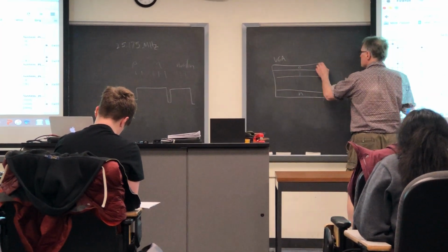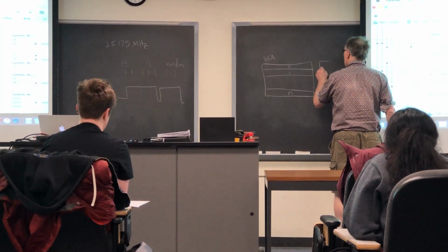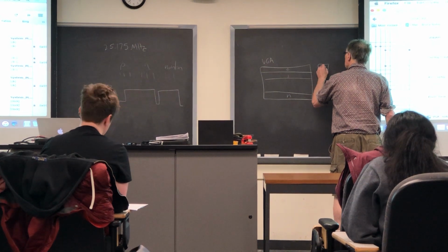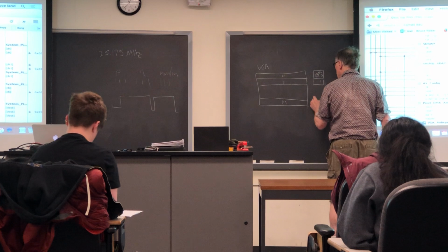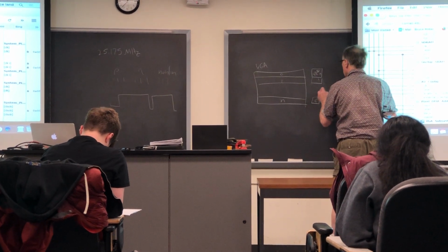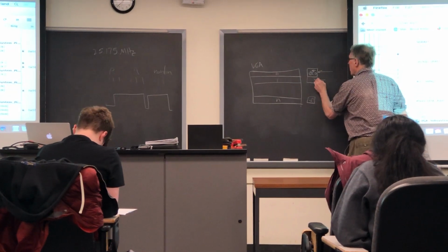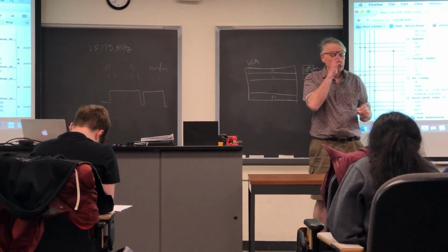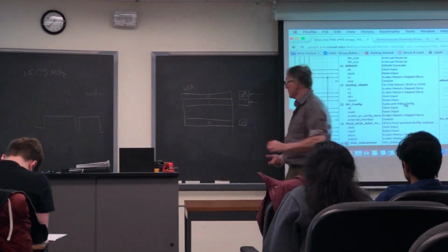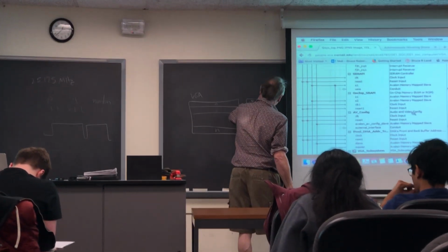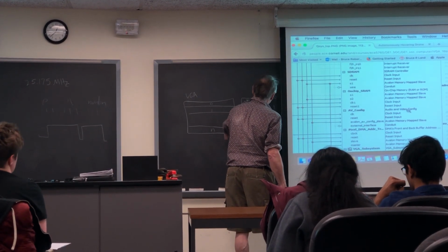And each one of these is going to be mapped into a separate RAM block: RAM block 0, 1, n. Each one of these is going to have its own dedicated solver, which can therefore write to the RAM with no contention, so it never stalls. Solver 0, solver 1, and so on.